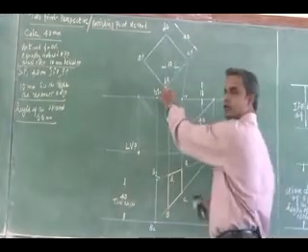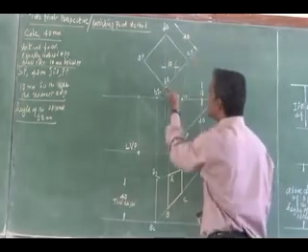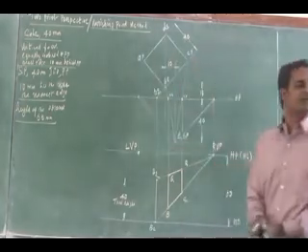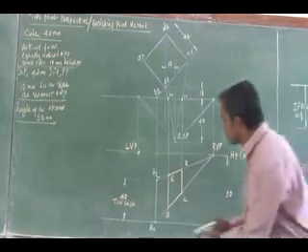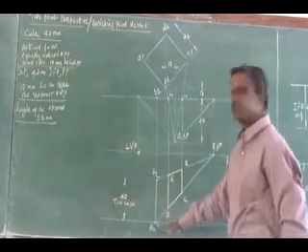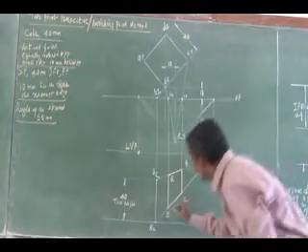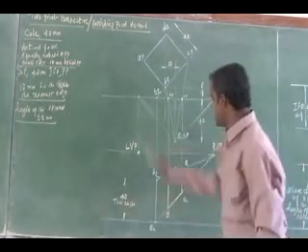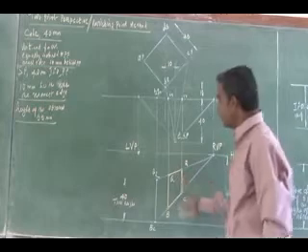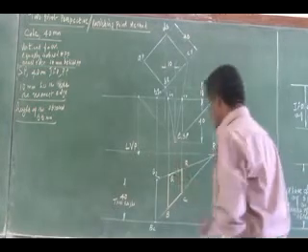So this edge is going to vanish to the right side. Also it is going to vanish to the left side. This edge BQ, I don't need to join this Q to B. Once I have got this face, this BQ, I can join B and Q of the perspective to the left vanishing point.